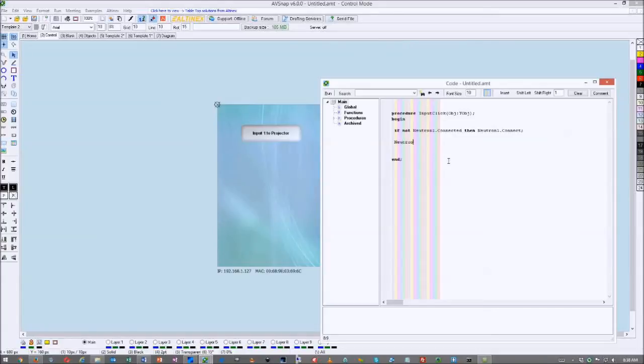So I'm going to put neutron 1, and I'm going to say write string. And you can see right here, write str. I want to write a string to neutron controller. And in this case, the string will be enclosed in 2 single quotes. And for this particular controller, I have to put this command. 2 triangular brackets RS1, that means RS1 is RS-232 port 1. Open bracket, I want to send I102 close bracket, and that's it.